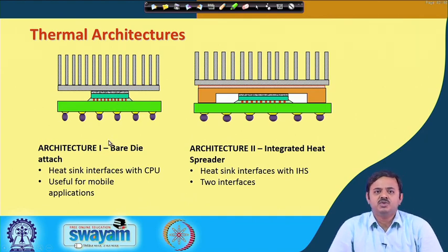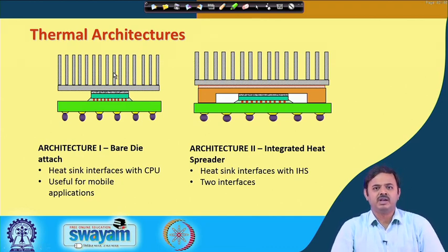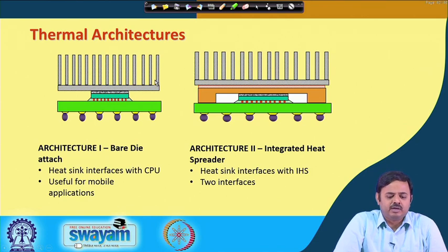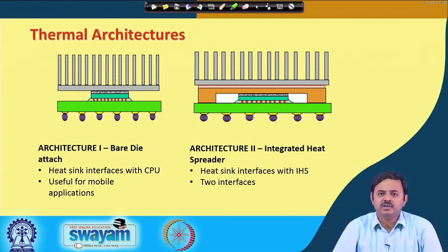Okay. So, this is useful in mobile applications. When I say mobile applications, it is not strictly mobile phones, it also means laptop computers, primarily laptop computers. Actually, this is not absolutely true, we will see that later. In a laptop, there is typically not a heat sink that goes right on the silicon, there is something else called a heat pipe, we will talk about that later. But bare die attach means that there is a heat sink or whatever the cooling solution is directly bonded onto the silicon with, of course, a layer of thermal interface material in between.